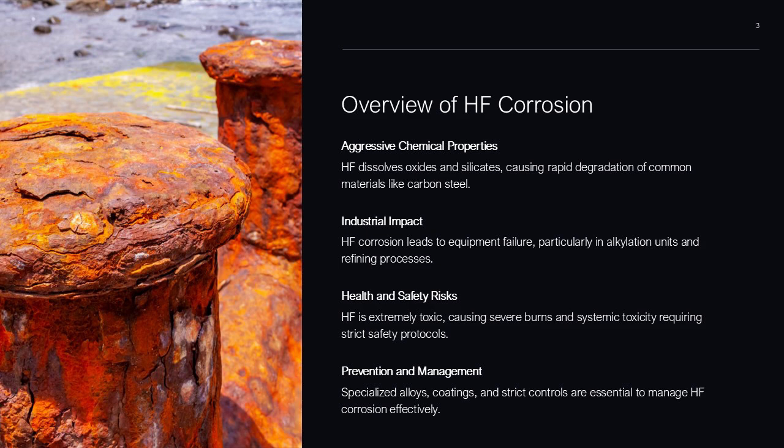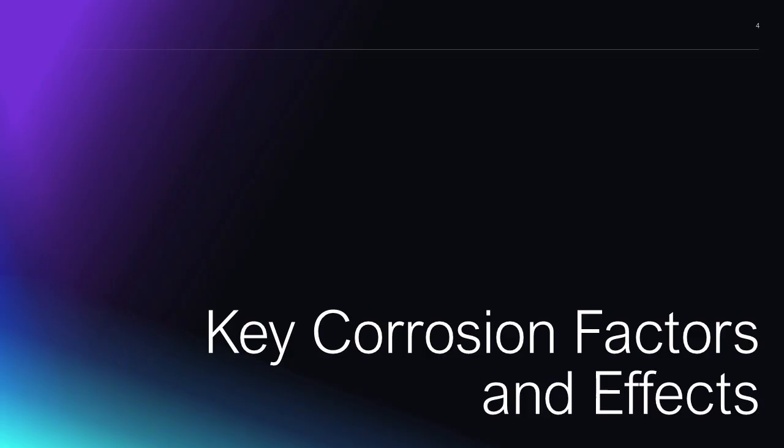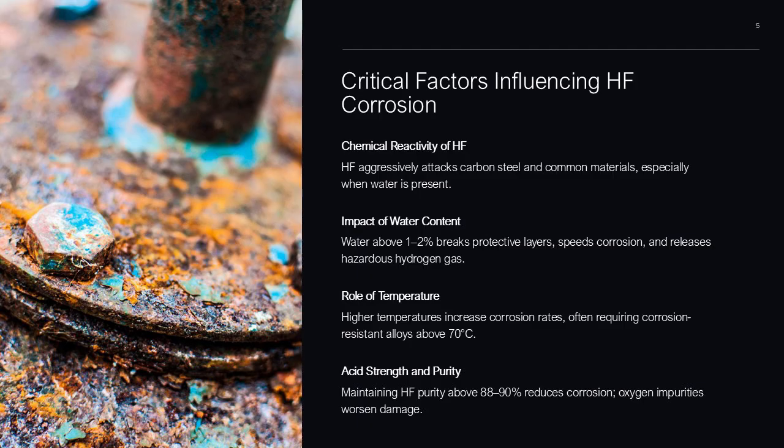prevent catastrophic incidents. Critical factors influencing hydrofluoric acid corrosion. Several factors significantly influence the severity of HF corrosion. High chemical reactivity is the primary driver, as HF aggressively attacks carbon steel and other common materials, especially in the presence of water. Water content is critical.